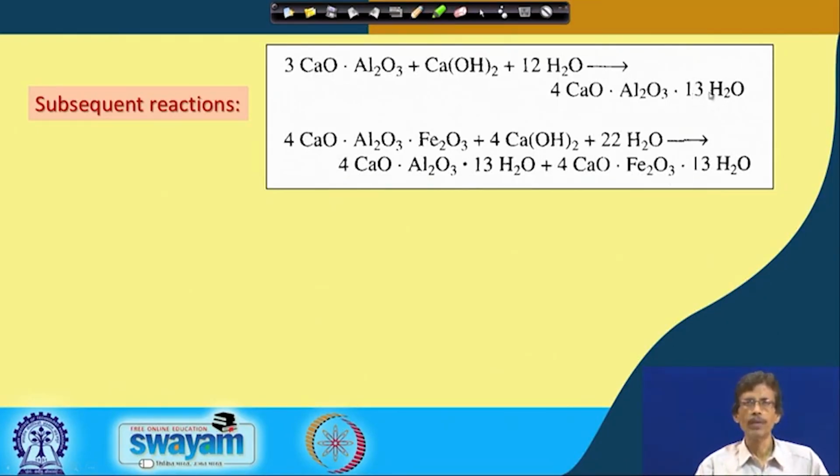If you heat it, these will be removed, and what remains is the corresponding material, that means all these oxides in the anhydrous form. If you take out this water, it will be hydrated through more OH bonds. More OH bonds can further be linked through a clipping arrangement of the hydroxides, so hydroxides can clip 2 aluminum centers or 2 silicon centers, or give the silicon-oxygen-silicon structure or the aluminum-oxygen-aluminum structure within the concrete.